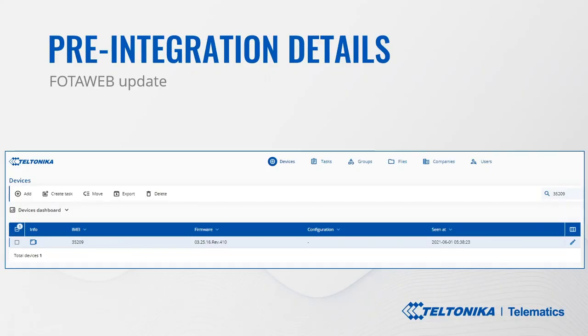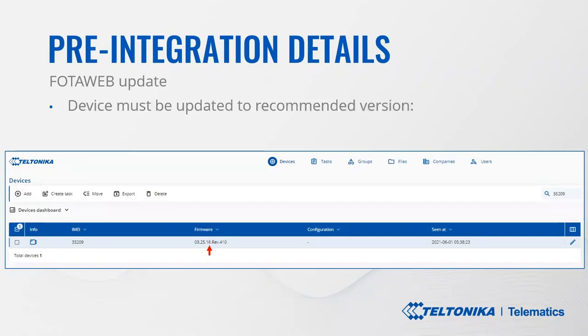To begin with the CAN unit software update, our Teltonika tracker must be running the current recommended FMB140 firmware version. Specified here is 03.25.16 Rev 410. This is the base version of firmware used for FMB140. Also, other firmware versions based on this branch can be used, so any newer versions that are already released.